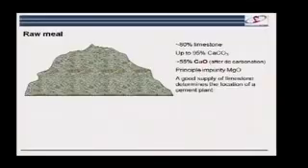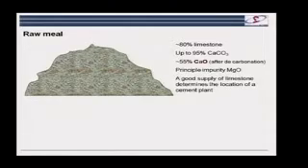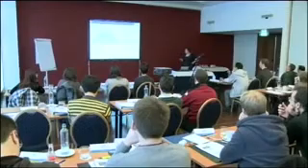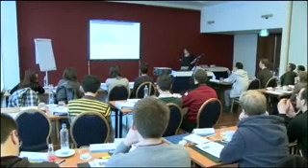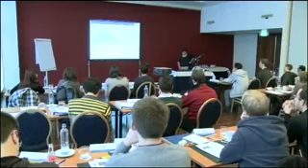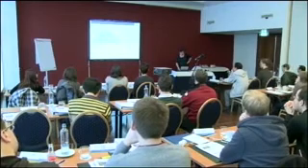So where do we start from? Well, we start from what's called the raw meal. And as I've already said several times, the basis of this is limestone. It's about 80% limestone. The limestone is usually pretty pure, usually up to 95% calcium carbonate. When we dissociate off the CO2, that reduces nearly by half to give you the calcium oxide. The main impurity we have is magnesium oxide, or magnesium carbonate more correctly. And as I've said, having a good supply of lime determines the location of the cement plant.